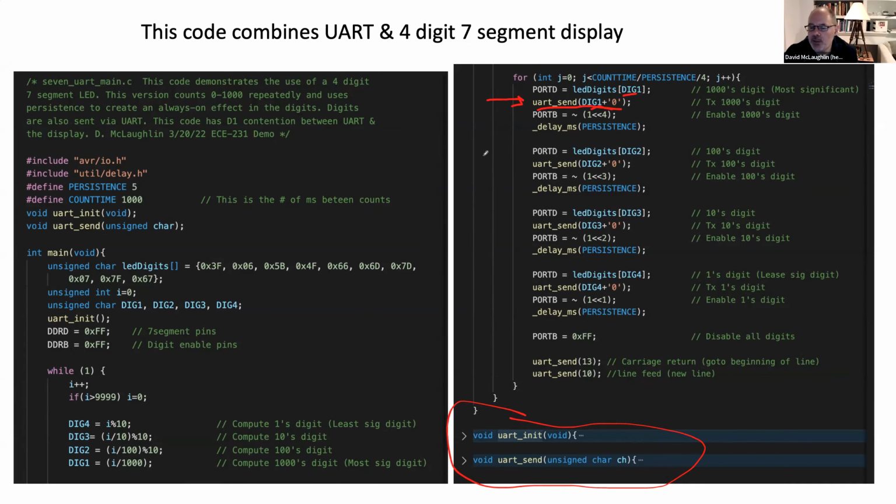And here's the issue. Recall from when we talked about the UART that the UART uses PD1 and PD0 for receive and transmit. We're only transmitting. And so since we're transmitting via the UART, we're making use of pin PD1. Okay, so let's just pause for a minute and take a look at this pin diagram. You'll notice that each of these pins has multiple things that it does.